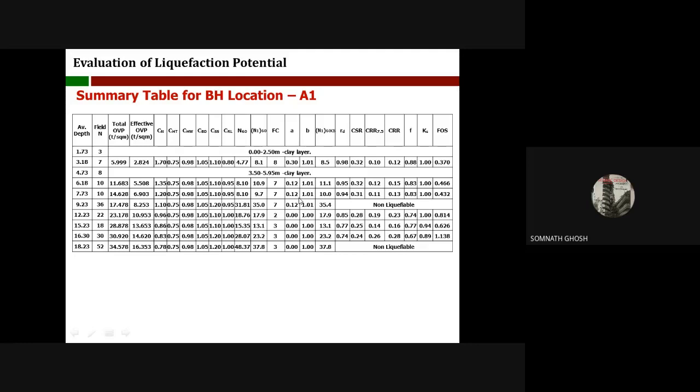During that period, they wanted to take the opinion of other experts on whether whatever they did was all right or not. In between, the 2016 code had reached the market. Naturally, when I assessed it, I considered IS 1893, 2016, and the pile capacity I found was not 60 ton. Then I told them to revise the pile capacity.